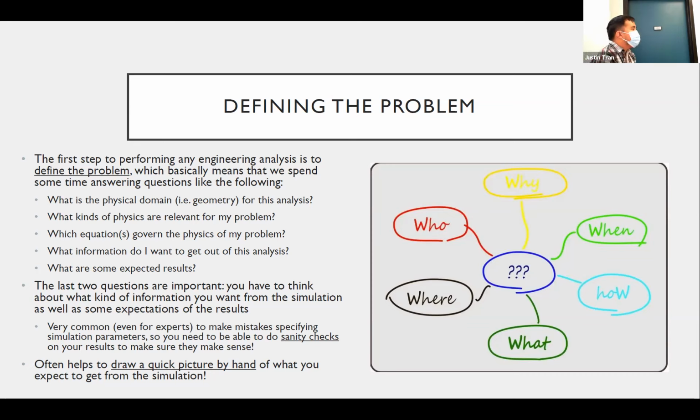You're going to run your simulation and it's going to metaphorically blow up. What that means is that you'll solve for velocities that are infinite, or that might not compute at all, so you might get infinity or not a number, or you might get pressures that are undefined. Those are results that are not correct.